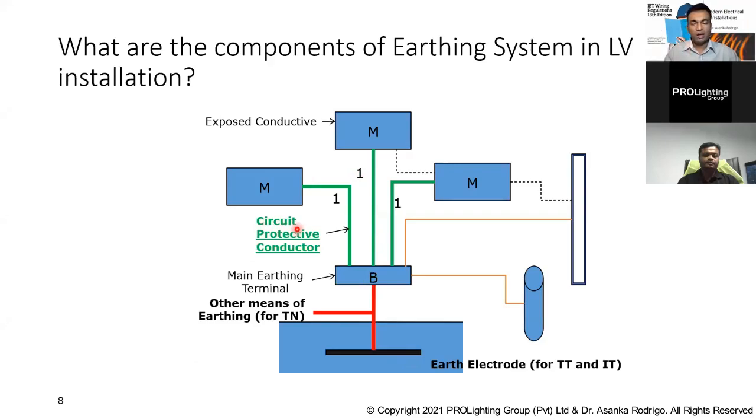That is number one. And also you can see there are some non-electrical equipment, for example a metal door or a metal pipe. In a certain abnormal situation or leakage, they can also get a certain voltage, and because of that we want to maintain their voltage level at the same voltage. That's why we call it equipotential. So to have that, we have to connect them as well. Those connections, the terminology we are using, is protective bonding.